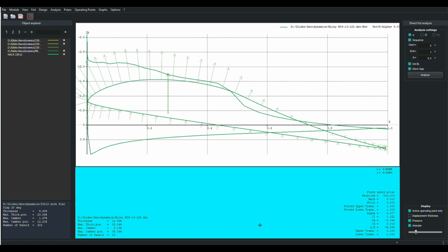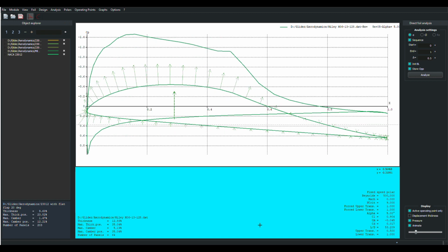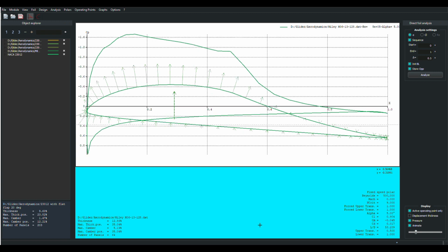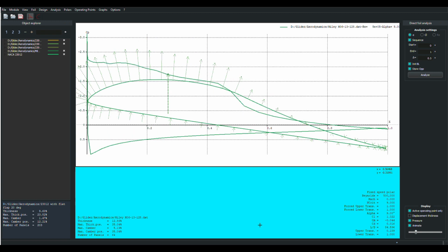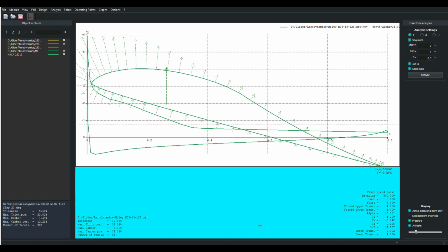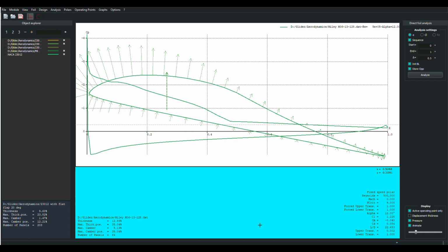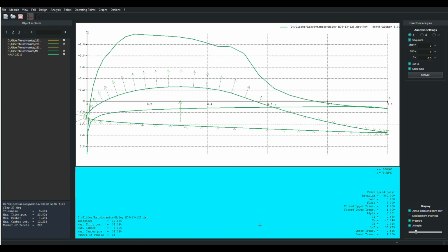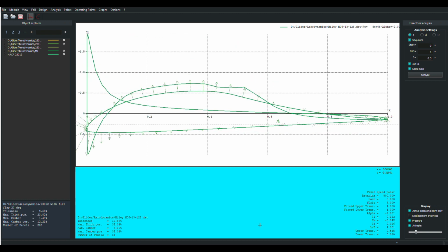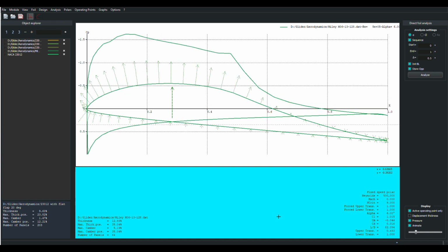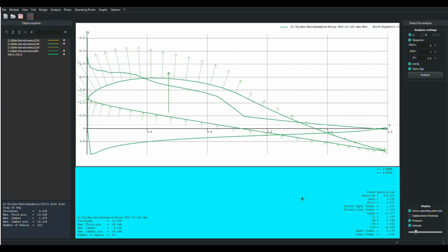And as that rooftop pressure recovery begins to develop, like there, that's where this airfoil gets really great performance. Tons of lift, lots of lift, with a minimum amount of drag to do the pressure recovery. And that's the nicety about designing airfoils in reverse. You can set a certain set of criteria, and then you'll get a shape that actually delivers that performance. Cool, huh? Yeah, gotta love aero theory and math, and when you get a powerful computer to actually work the problem in reverse. It's cool. Once again, thanks to the developers of Xfoil.